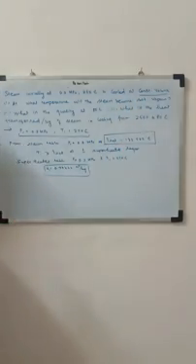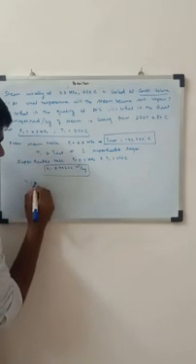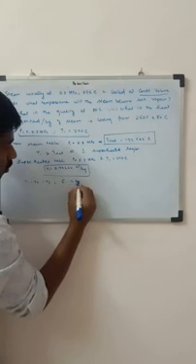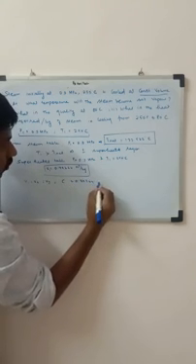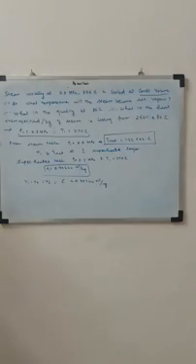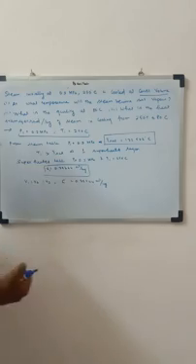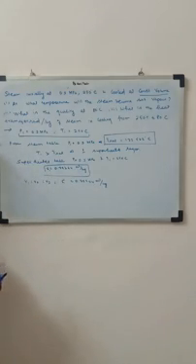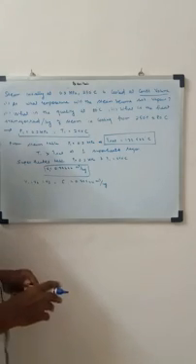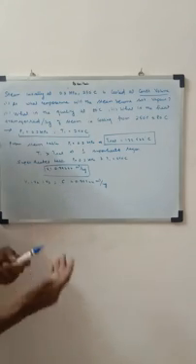That means our V1 is equal to V2 is equal to V3 and so on, equal to a constant, which is 0.79644 meters cube per kg. This volume remains constant. What is the first question? At what temperature will the steam become saturated vapor? He asks us, if I keep this volume constant and reduce the temperature, at what value of temperature does the steam become saturated vapor?